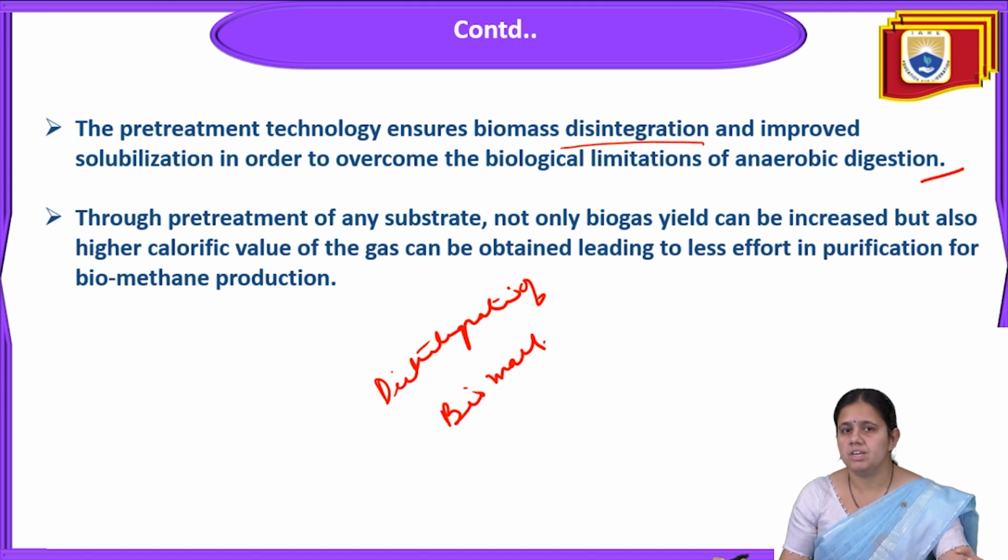If we do not do the pre-treatment before adding it into the chamber, then what happens? The process will not take place completely, and the hydraulic retention time will also increase. So to avoid this biological limitation, the limited activity of these microbes, this pre-treatment technology is used.